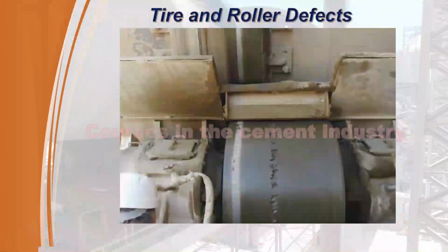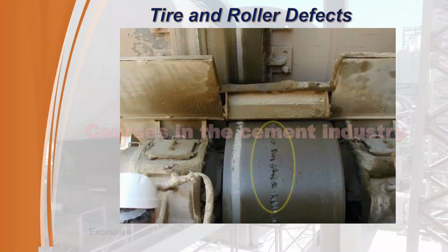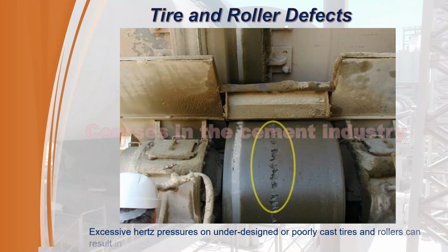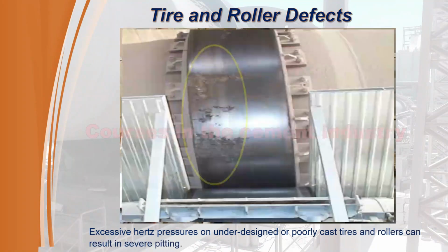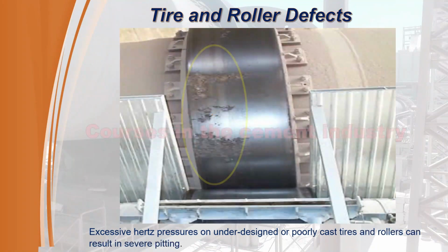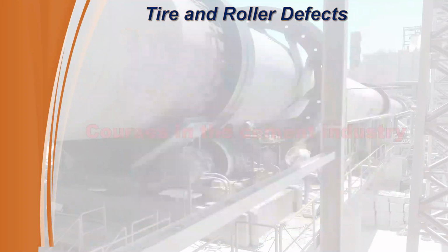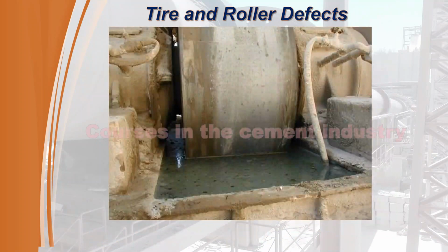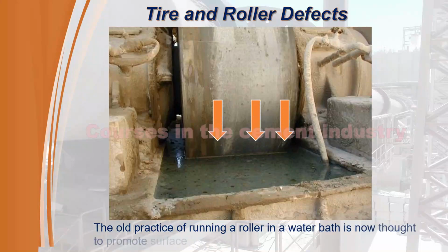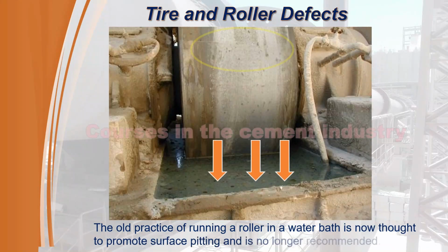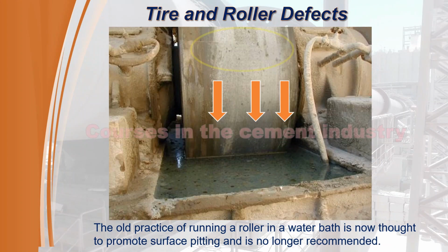See in this figure. In this case, excessive Hertz pressures on under-designed or poorly cast tires and rollers can result in severe pitting. See in this figure. In this case, the old practice of running a roller in a water bath is now thought to promote surface pitting and is no longer recommended.